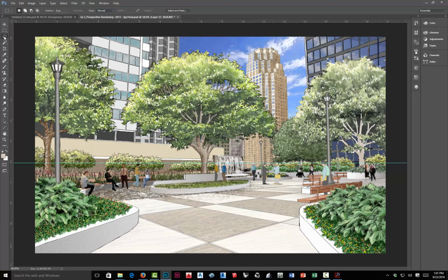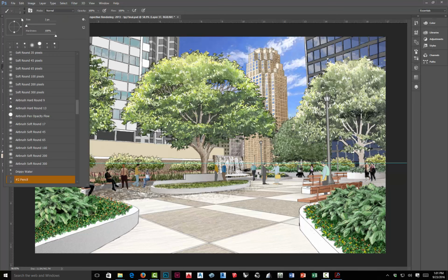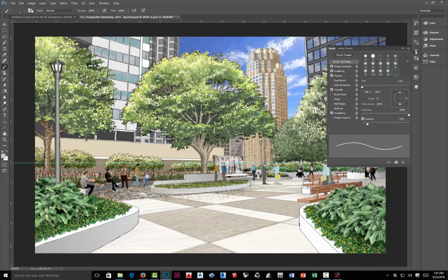So if I go down to this, you can see that this lasso selection tool actually is set on add because that's the last time I used it, I had it there. So when I go here, it's back to replace. Here it's on add. So each of these tools maintains its own options, and the options change. When I go down to my paintbrush, now I've got a whole different set of options up here. I can control pressure sensitivity with a pen, adjust opacity or flow. I can pop up a list of all the brushes I have here. I can pull up the brush panel if I want to make changes to a particular brush.